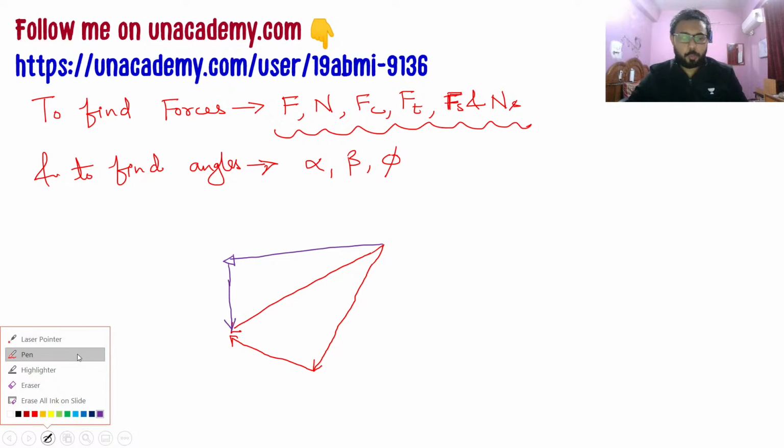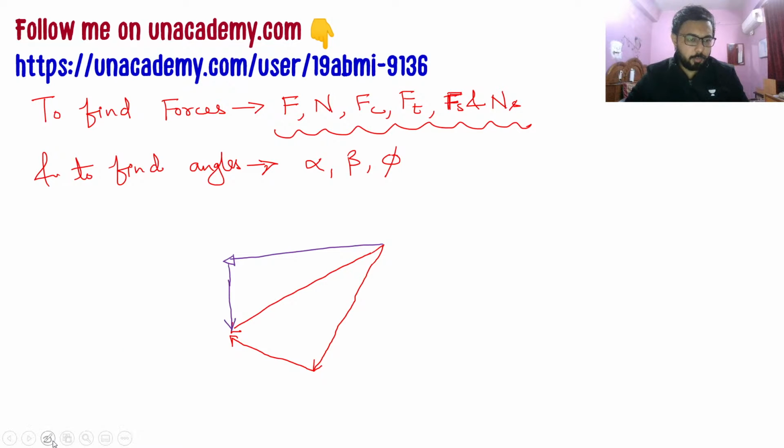All six forces will be shown in the diagram that I am drawing, and this diagram will be very important for your calculation, and by using it you can calculate the forces. There are some relations obtained from this diagram that we have to see, but there are other formulas by which you can also get the forces. I don't recommend learning those, because they are very lengthy and you will have a difficult time remembering them. So if the question asks you to find forces and angles, use the Merchant circle only.